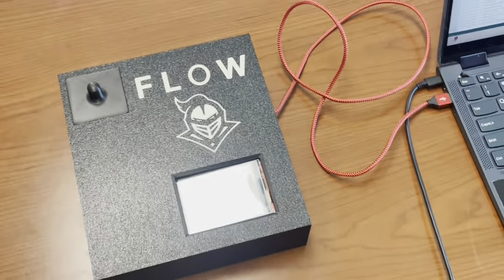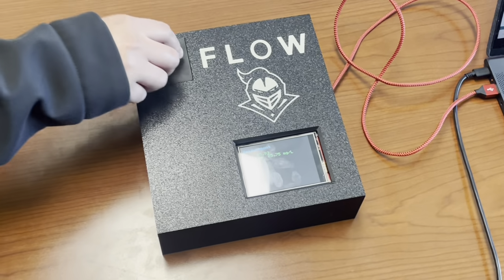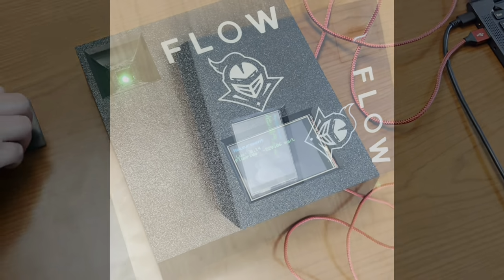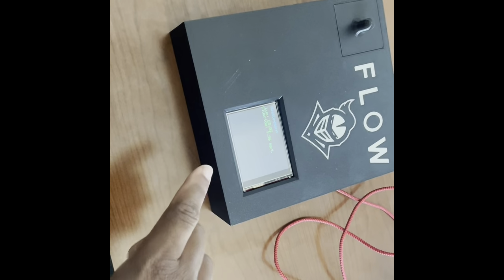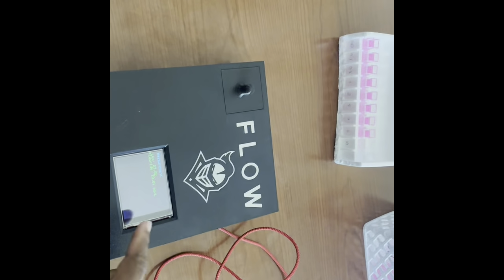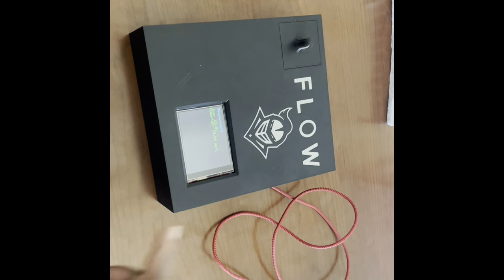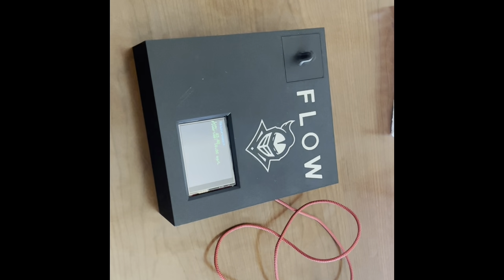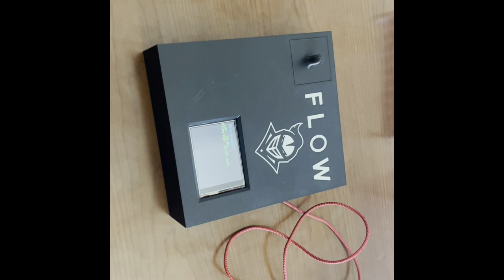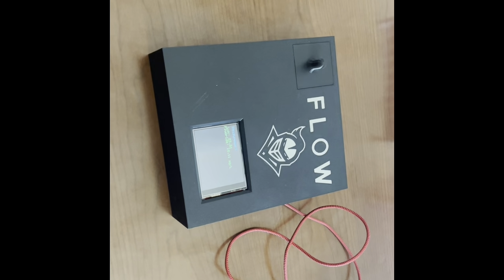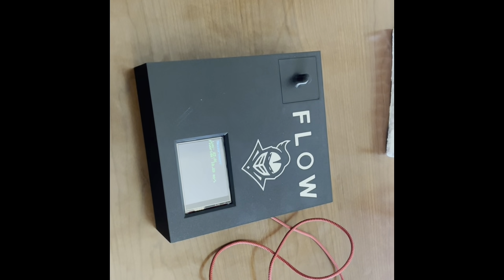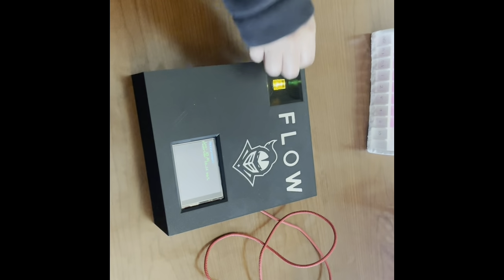Okay, great. So now we're in our measurement phase. Through all of it, you can see that it says the number 10 is in, and that it's detecting 10 milligram per liter of fluoride concentration. So now we have calibrated. In our measurement phase, we are confirming that there is 10 milligram per liter of fluoride within our cuvette sample. So we'll try.